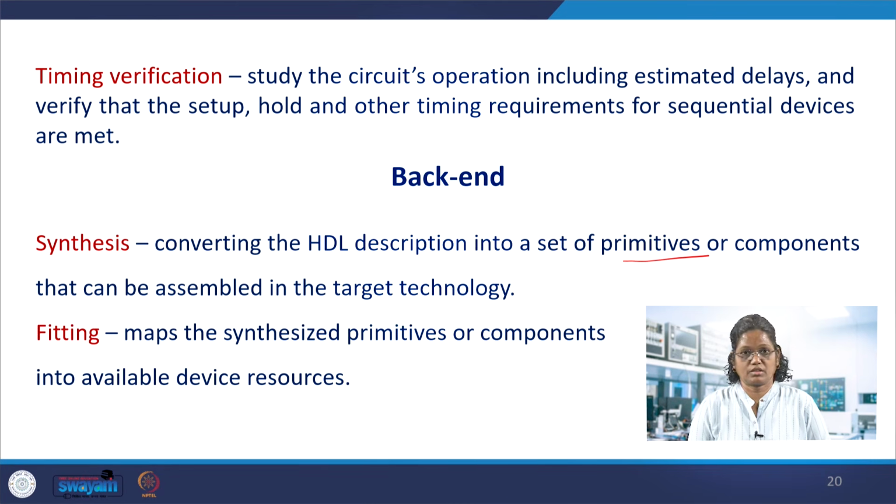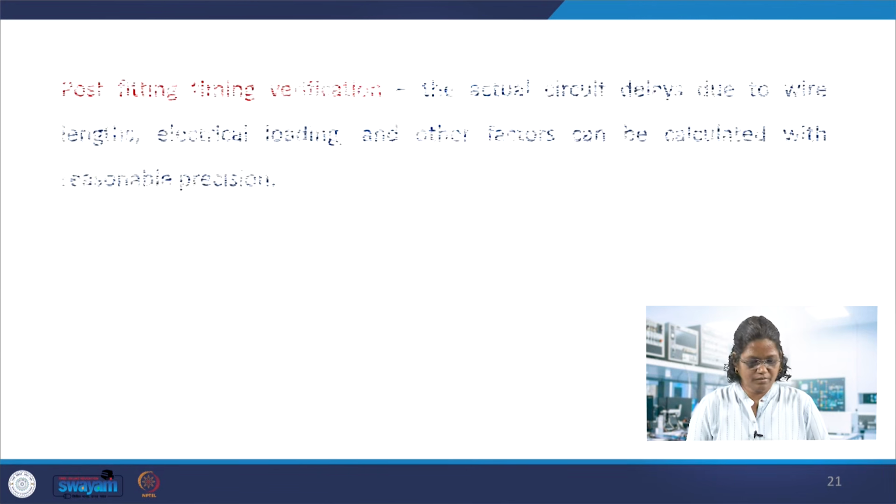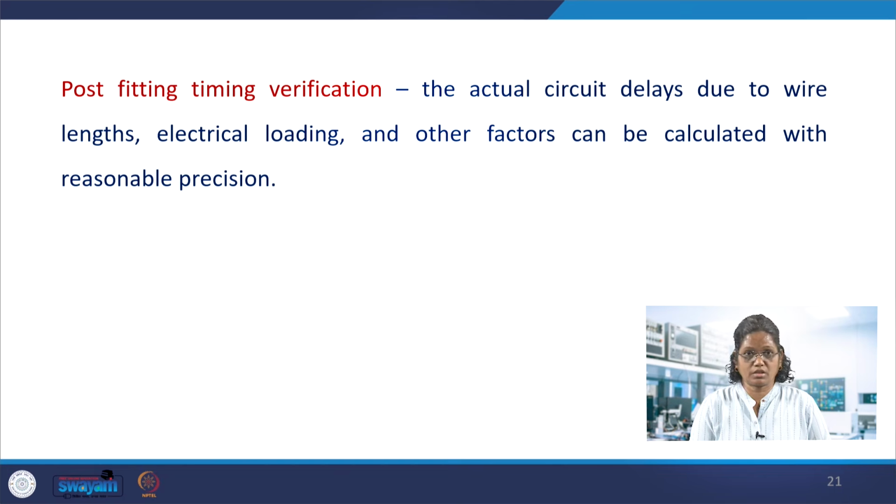Fitting maps the design onto the device resources, and after post fitting the actual delays are all considered. It is calculated with all the timing delays, and some functional inputs are given at this stage to verify whether the design is proper after post fitting.